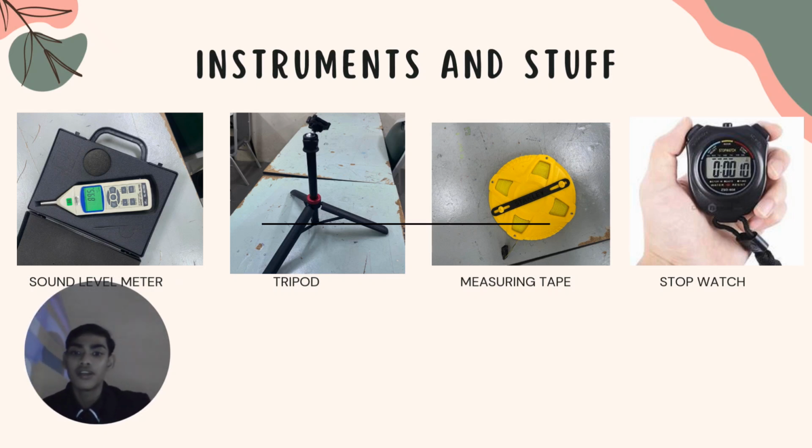For the tripod, it is to ensure accurate readings. The meter is mounted on a tripod to prevent hand movement or vibration from affecting the result and to keep the device at a consistent height. The setup maintains standard testing conditions. Third, a measuring tape is used to correctly set the distance and height of the meter from the noise source. And lastly, a stopwatch is used to make sure that measurements are taken over a precise and consistent time period, as required by noise assessment guidelines.